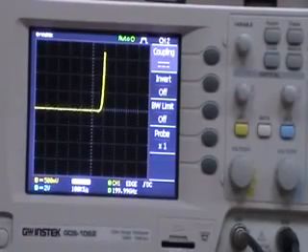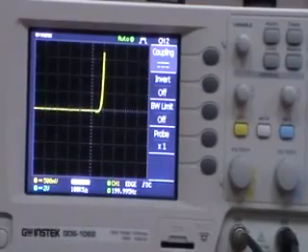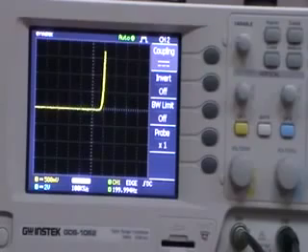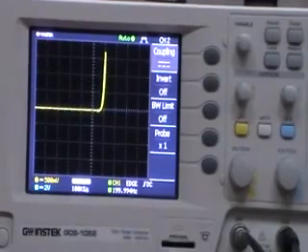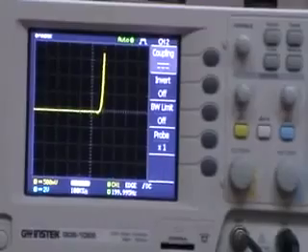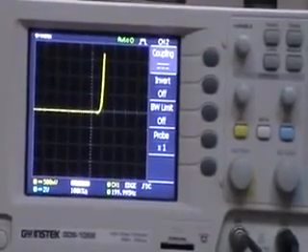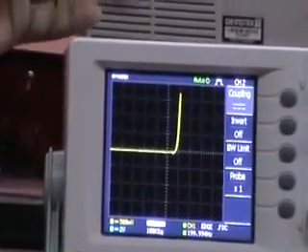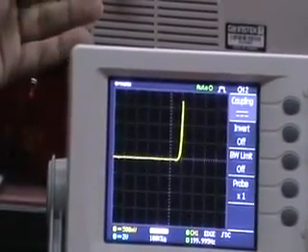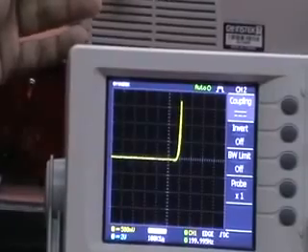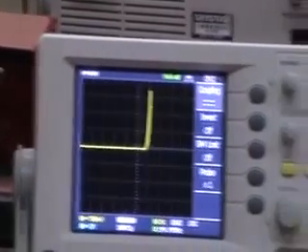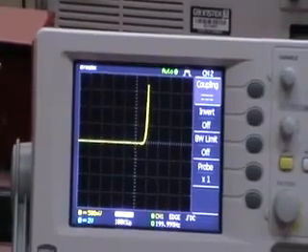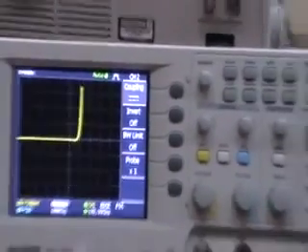The final step of this experiment is to find the diode forward resistance by measuring the slope of the conductive region. In this linear region, we should take two V points and I points, and by finding the slope of those V and I, we will find the diode forward resistance. By completing this, the first part, the IV characteristics of the diode, is completed.